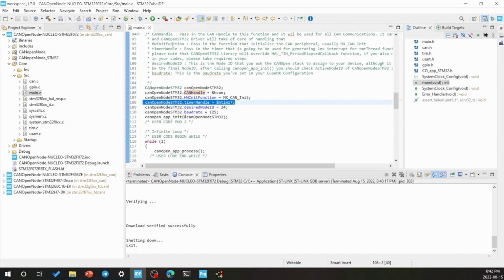Here we need to pass in a timer handle. Basically, that timer fires up. I mean, the interrupt fires every 1 millisecond, or you can even configure it to do a smaller step for more accuracy and less jitter. So this is the timer that we configured. And just a quick note that we'll go through all these in detail later on when we are writing the code for our own custom board, okay?